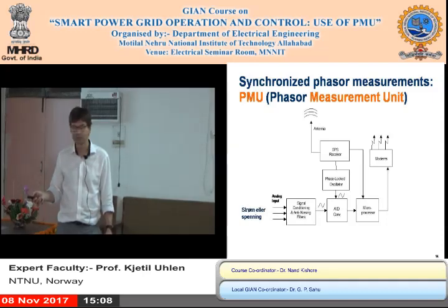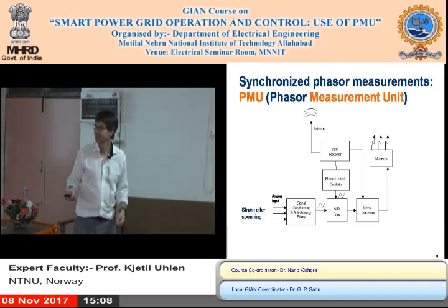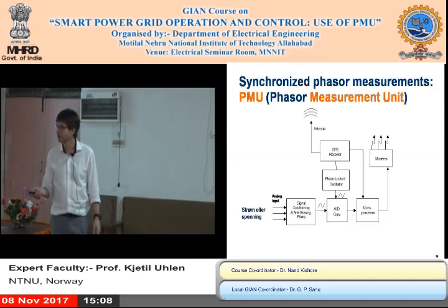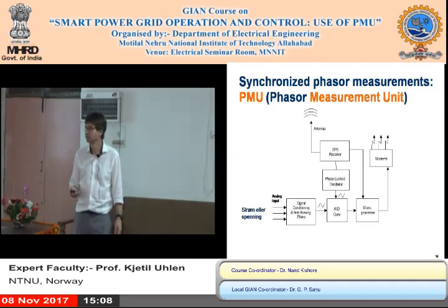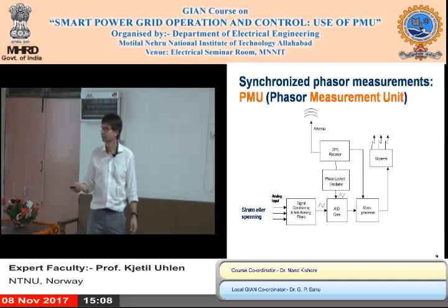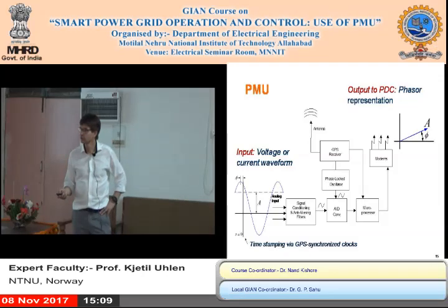Make it an Ethernet port or something, because that's what it usually is. The point is that you communicate. You stream the values out of this, the phasors. Is that okay? So that's how it goes. 50 Hertz signal input, 1 phasor output.